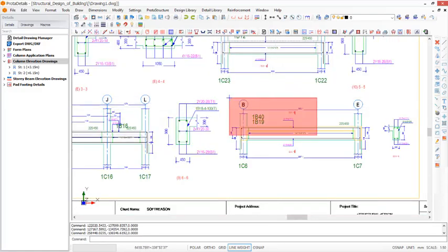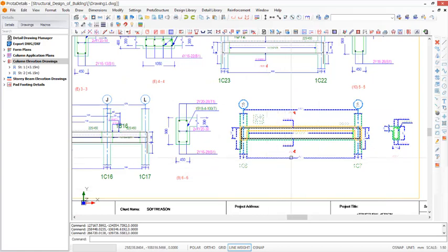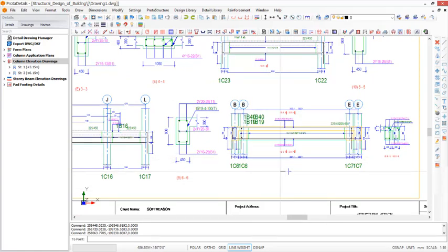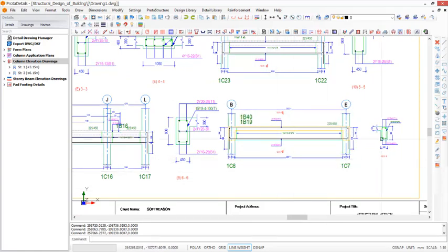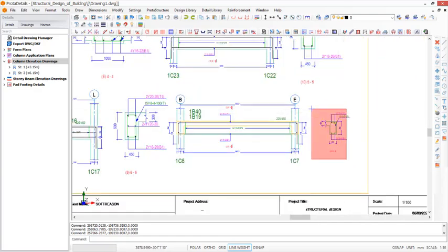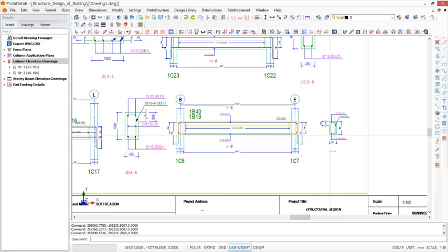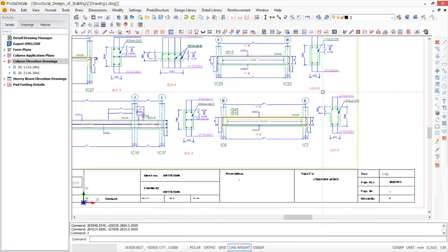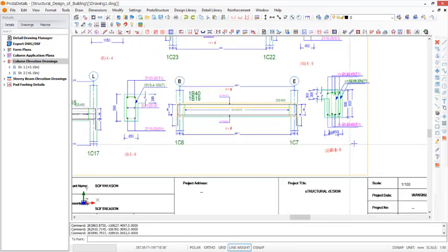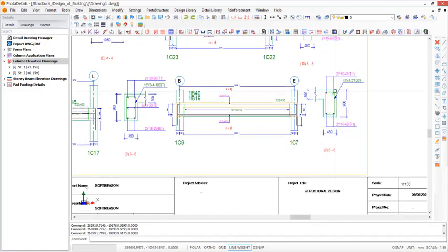So you can adjust this by selecting all of this particular drawing, move it a little bit, go down to these provisions. So you can scale this now up. So do scale, enter, pick the base point, and then for the scale you have to key in the value and enter to have this. Okay, so try to adjust it in a way that it wouldn't clash with other drawing entities.